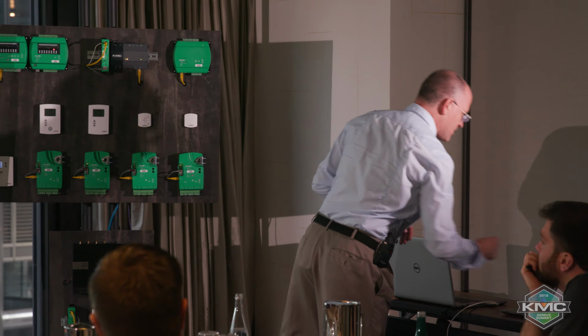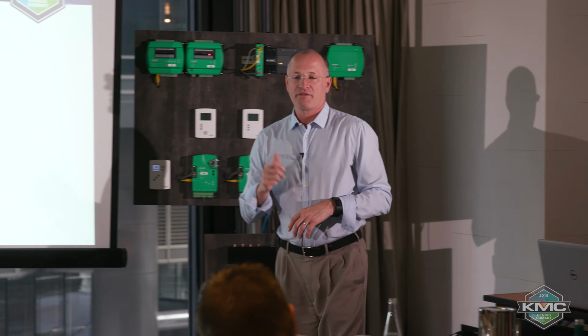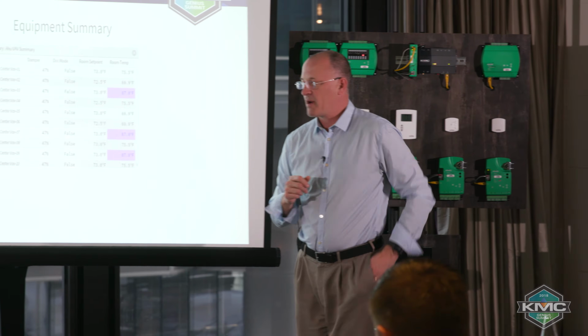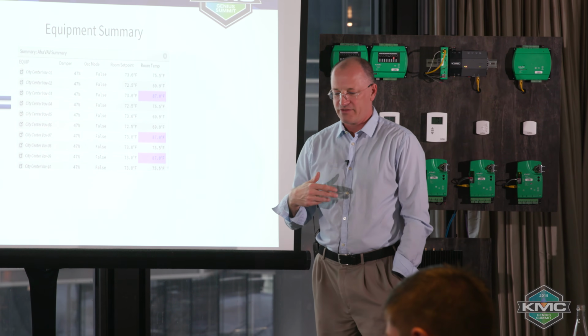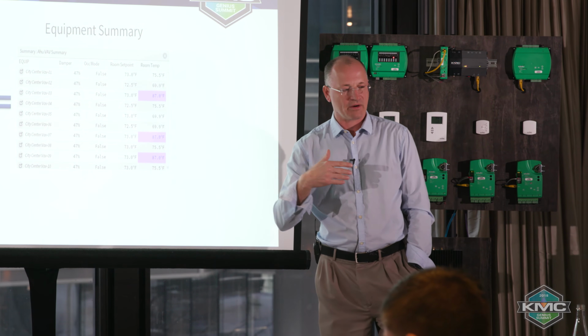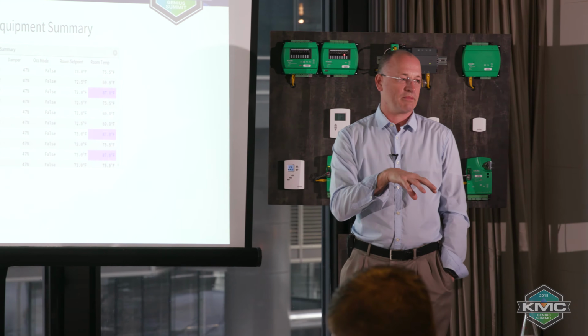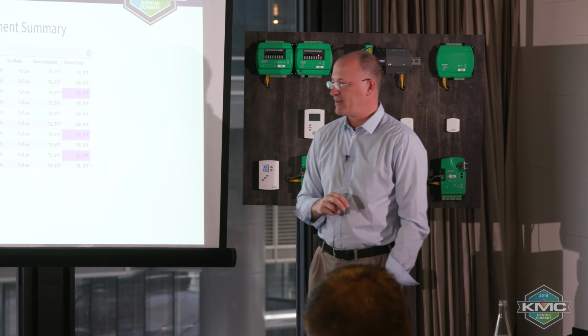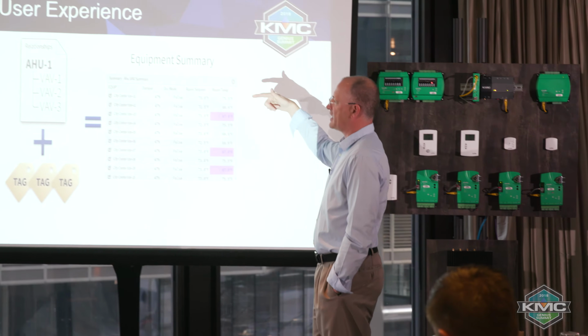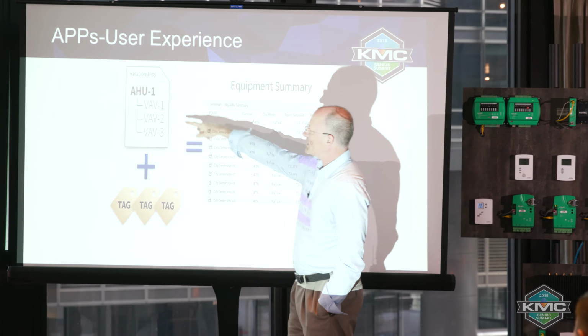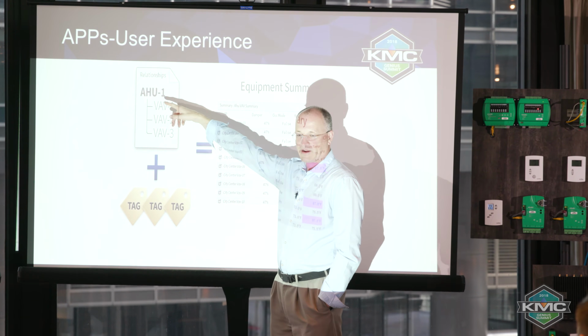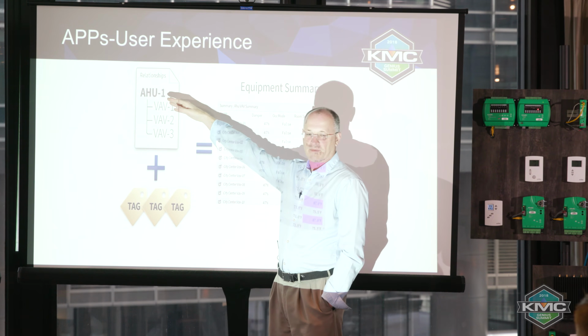All right. This is the one that leverages reference tags. So remember, the relationship tag that this VAV is getting its error from error handler 1 is in each of the equipment records for the VAVs. So this particular application, as an example, would look at those relationships and run a query against all pieces of equipment.